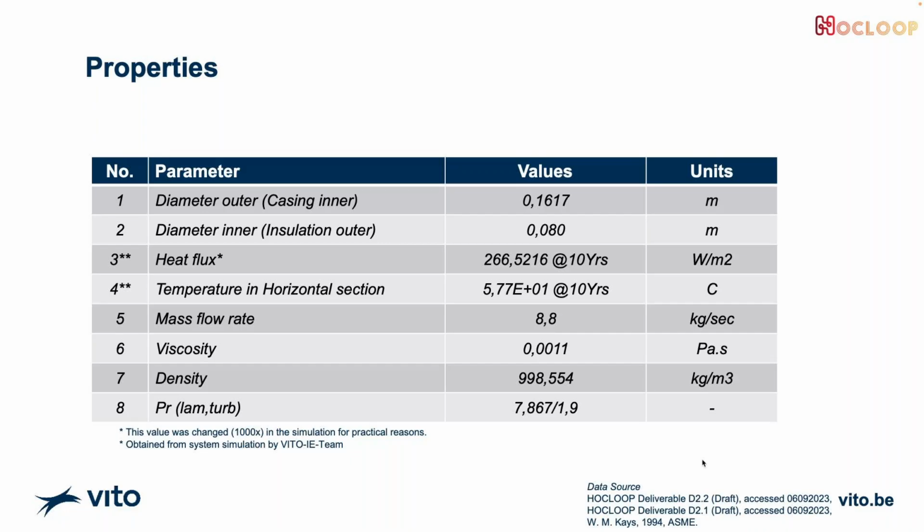So you cannot use streamwise periodicity then? No, apart from that. Okay. It's an internal flow question. I hope it will match. Also for some other pin fins, I think we have done some internal studies, and I think they correlate for most of the cases. If you have multiple fins interacting, for example, then you have a huge impact of turbulence, because it defines when the flow becomes very turbulent, and then you have unsteadiness. If you are capturing everything, then only certain turbulence models can give you a very exact match.